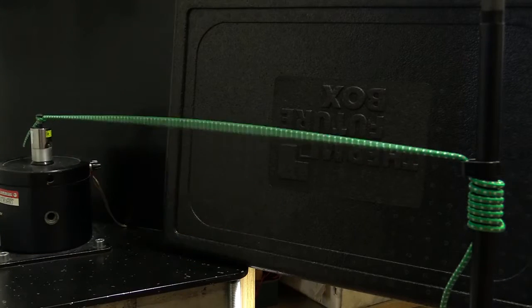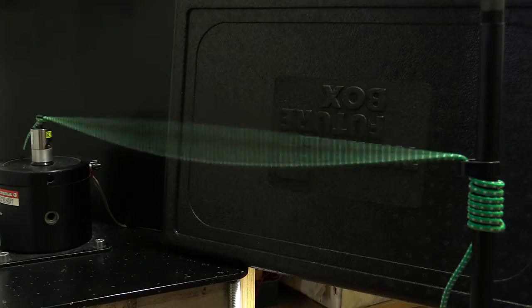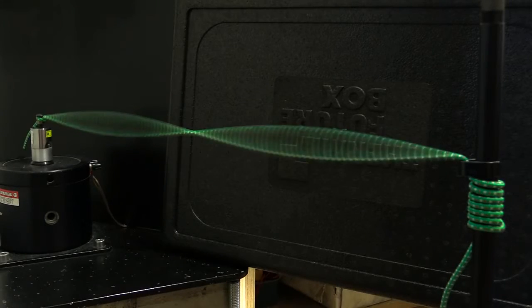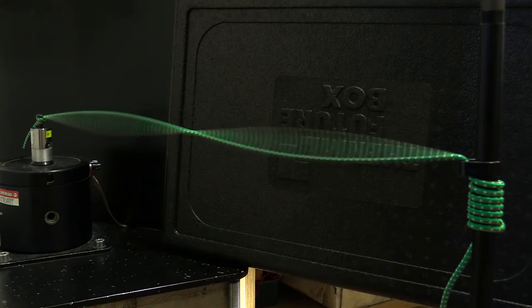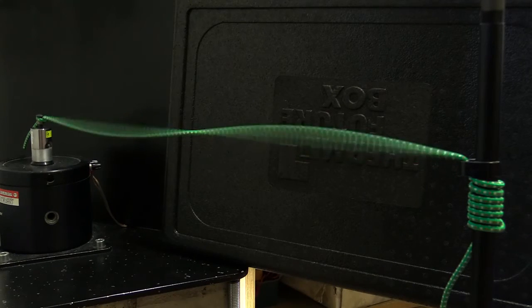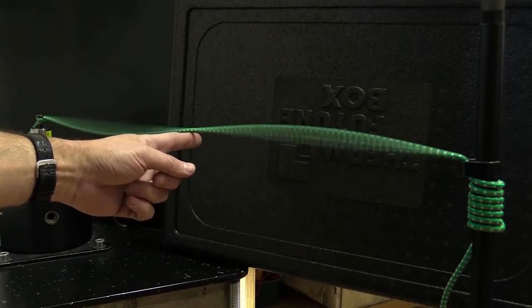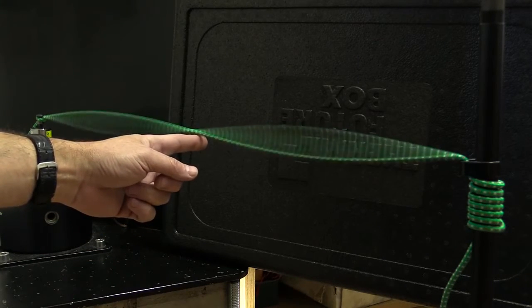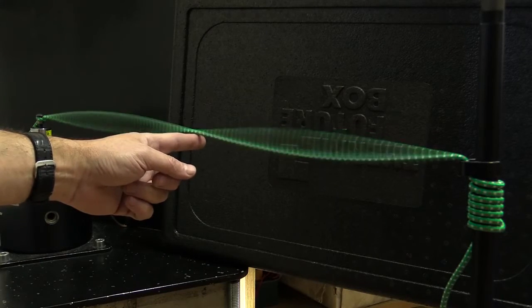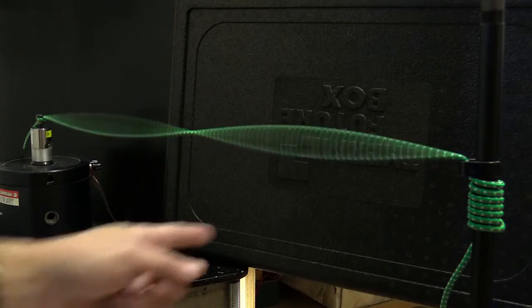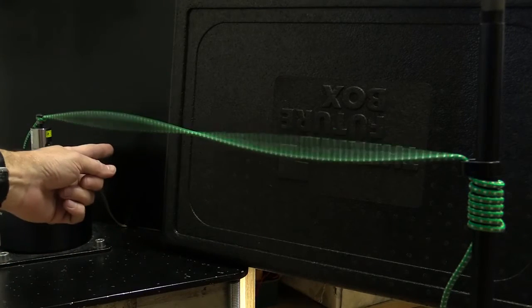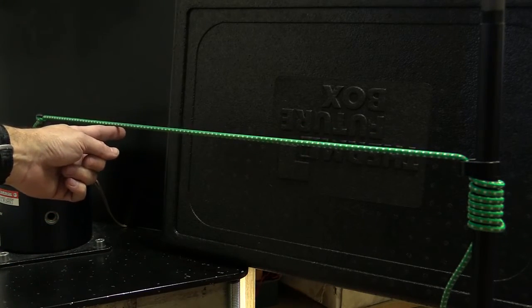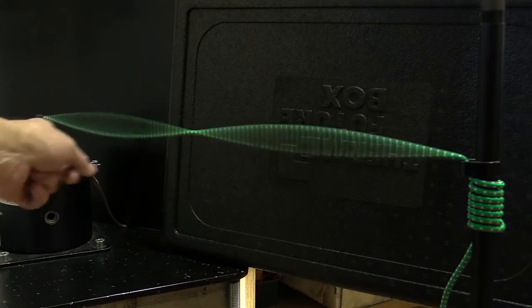But the second mode shape could be the problem sometimes, not the first. Now you can see the second natural frequency. The location of the pillar is now much more important. When I add it in the middle, then the vibration remains unchanged. I must add the pillar here or here, or use two pillars.